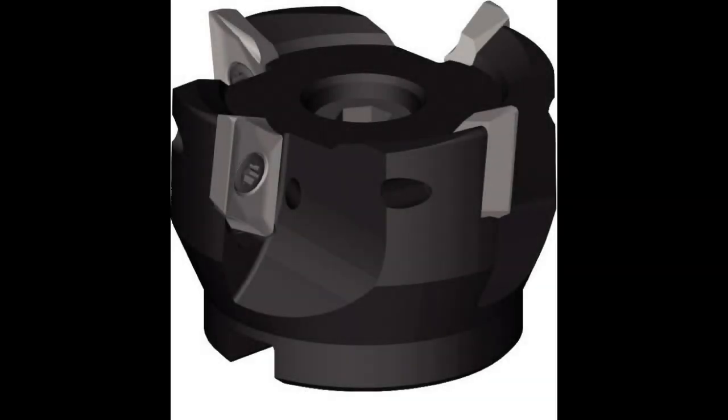Okay, here is shown an example of a shell mill, face mill, typical of what you're going to be using. We have a 3-inch Kennametal 4 flute or 4 insert shell mill, face mill. Now, face mill is the type of cut it makes, and shell is referring to that it's a non-cutting body that bolts onto an arbor, acting like a shell around the arbor, and that is the black component you see with the nut or the screw in the middle.